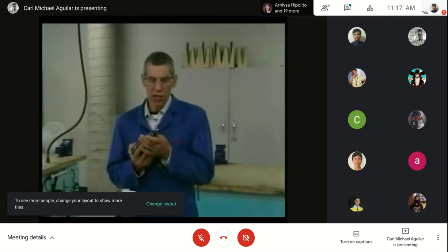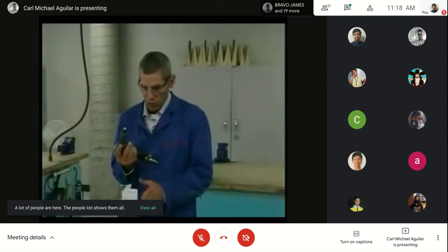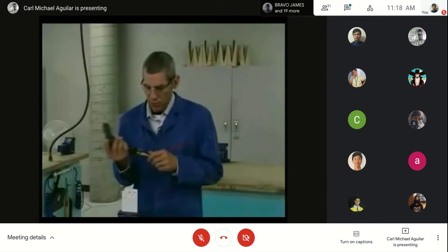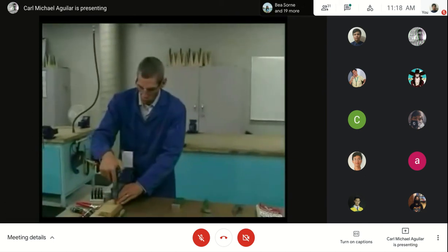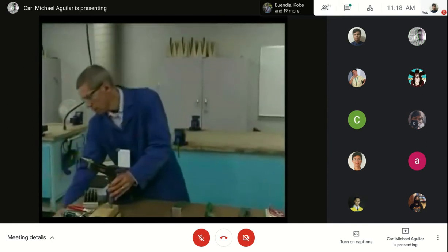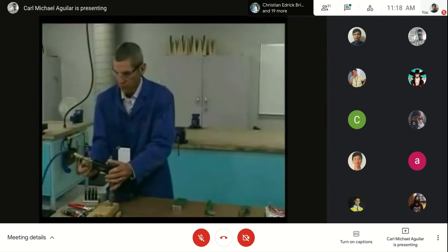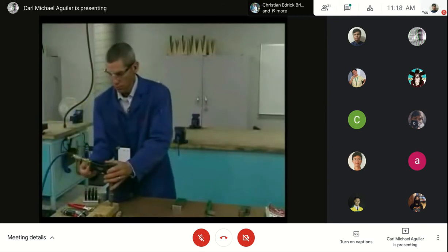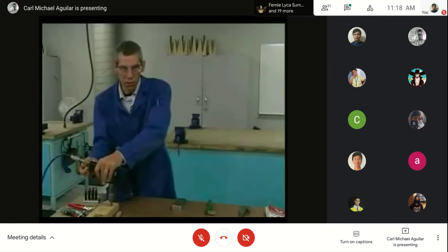So we've selected the correct rivet gun, and we've got the bar, and with the correct rivet, we're going to set the gun. To set the gun, have a block of wood, a 2x4 or 1x4 or some piece of scrap wood. Don't use the workbench. Plug in the air line to the gun, and I'm going to turn it down at first, to make sure that it's not hitting too hard, and then you're going to pull the trigger fully.